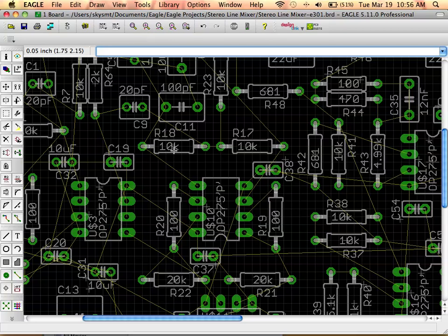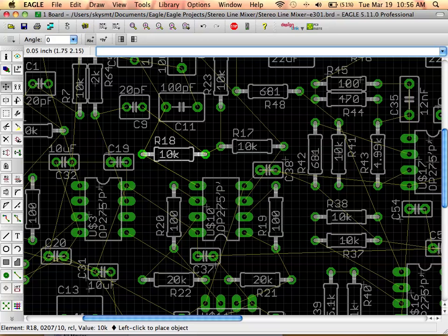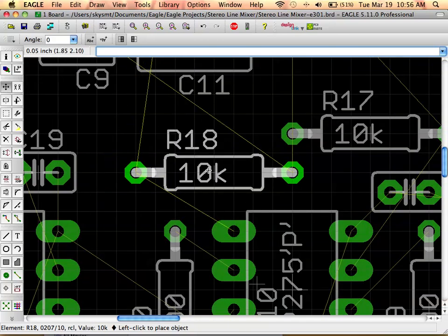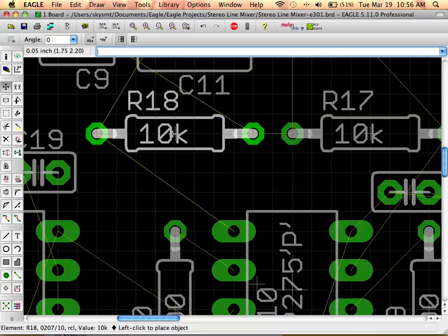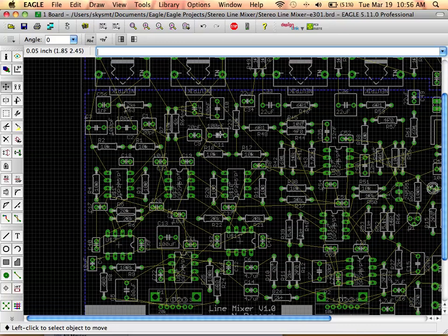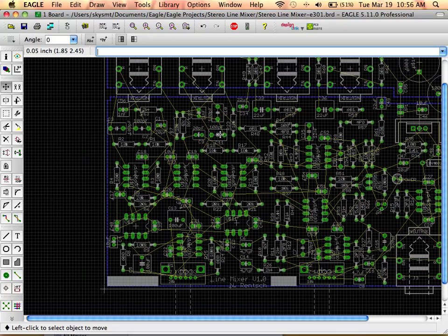So if I want to move something, let's say I want to move R18, I'm moving it integer amounts on the grid. The router has its own grid as well, and this is the grid it uses to navigate the board, for any traces that navigate the board. You can think of it like driving through a city. You can only turn where there's a street, right?